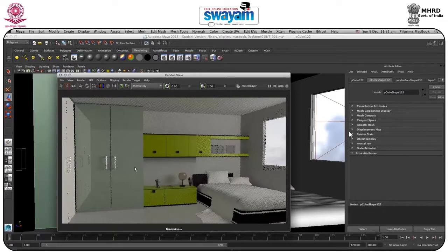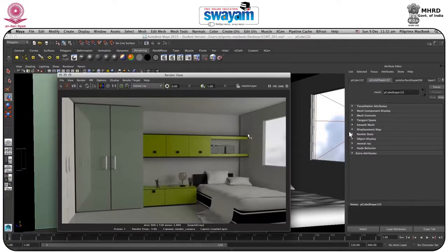And just do some much more tweaking in this. So we'll start working on tweaking. As you can see, this part is getting shadowed, which is good because we use only one light. Now we will use two or more lights, and we'll look at the render, and after that we'll increase the amount of final gather and global illumination. So as we have applied the blend, it's reflecting quite well. And okay, we'll not glow this thing because it's morning and we don't need to glow all the things.